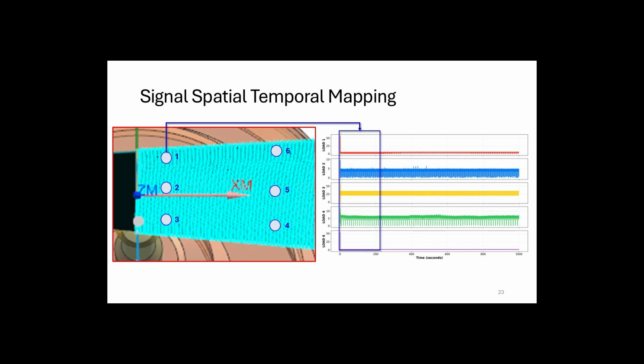And if we compare that to actual control position, if you blink, you miss it, you don't really see that much of a difference. From here, we can discern which signals are most important, because we're collecting like 15 different process parameters, but not all of them might be important for the prediction step. So this is one step to figure out, from all the parameters we have in the different operations, which process signals we should focus on for the most accurate prediction. That way we're not doing extraneous calculations or making extraneous database, which can also speed up computational time.